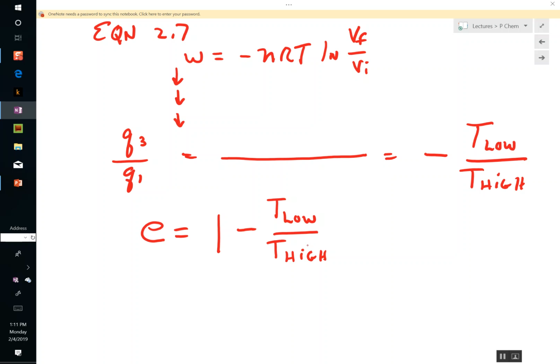It's condensing back down around room temperature, and the coal is creating the steam at some temperature. Is it 100 degrees centigrade or 120? You have this differential between where the steam is going to recondense and how hot the steam is that's moving the train, and you get the efficiency of the train just off of the two temperatures involved.